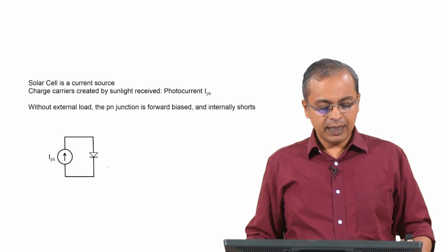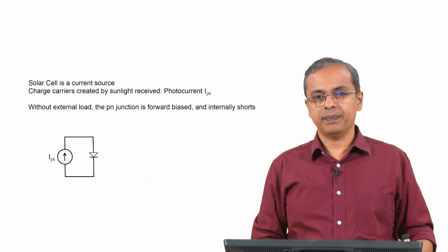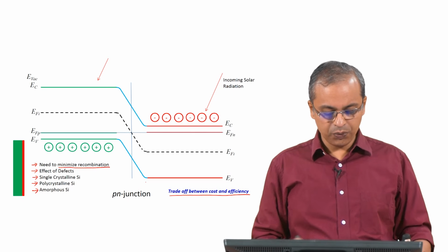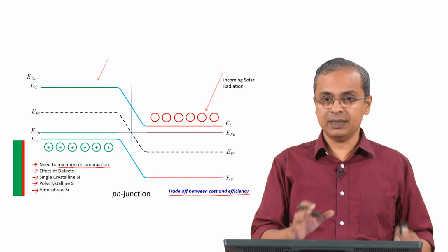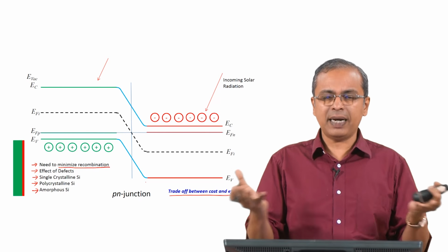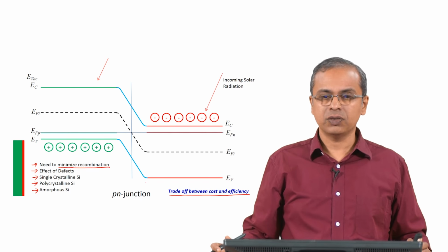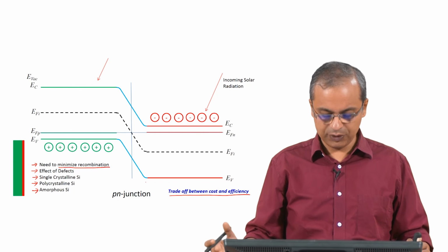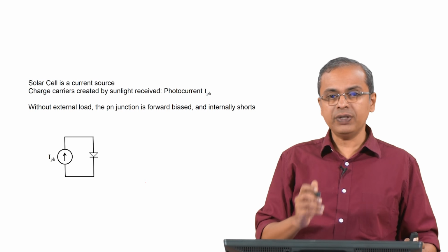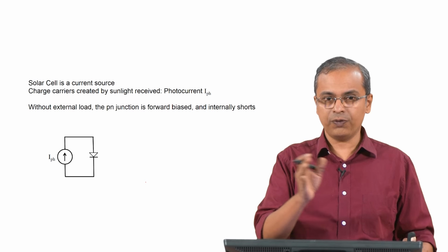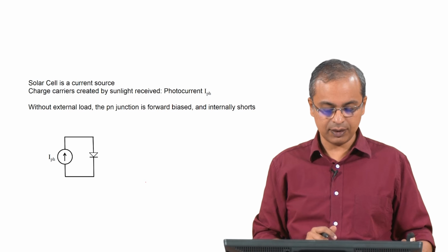Now that you have created this p-n junction, and you have seen how you can separate out the charges, you can actually generate electricity. I mean, you can tap this, now that you have separated the charges. Even in a battery, you have got a source of electrons, and those electrons will come through the external circuit and go to the other side. So, anode, cathode you have, and then you have some process by which you utilize it in the external circuit. Similarly with the solar cell, you have now created a situation by putting this p-n junction that you have separated the charges, and these charges can flow in the external circuit.